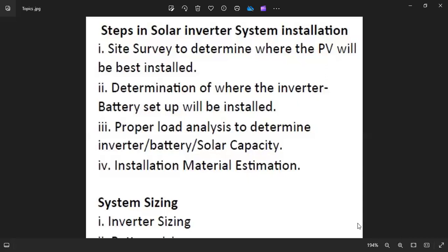Its own concern is when this setup can actually have an issue with the charging system. When the charging system becomes faulty, it can send a lot of current to the battery. In such cases, this battery can emit a lot of toxic gases. You understand? A lot of toxic gases can be emitted from a battery, especially the sealed lead acid battery that is sealed. It will emit a lot of toxic gas.